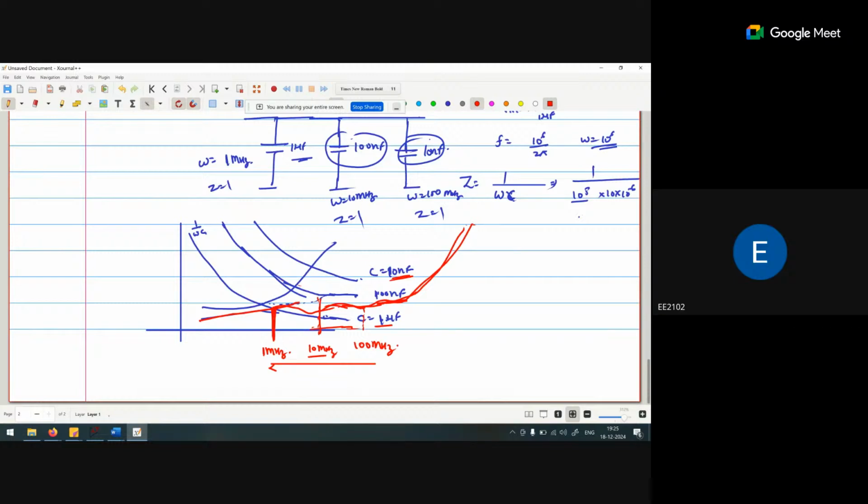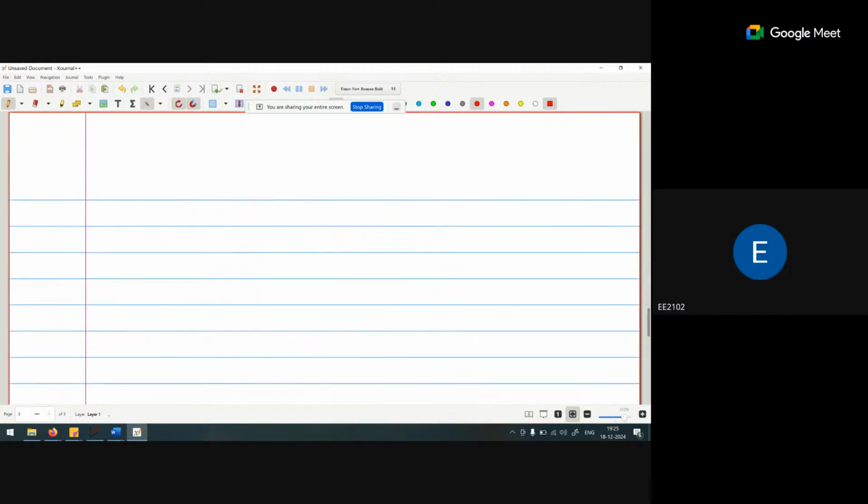Okay, so in the output, if I am using multiple capacitors with different values, we get the maximum span where this will be operating. Now if this is my capacitor, what is the equivalent circuit of this one? If I am using the capacitor, this particular SMD component, its leads, its terminals will behave as an inductor. Why? Because it is a wire. When the current is flowing through that, sir, yes, one small note.